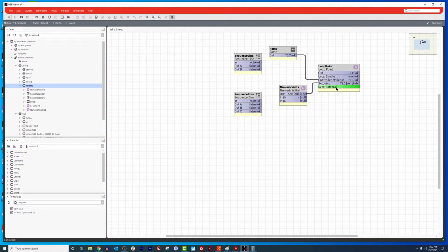Well, you first check whether you have a bias or a setup value. If you don't have a bias or setup value, and you have a proportional value and it's accurate, and you are below set point on a direct acting loop but you still have output, that's most likely integral windup. And that tells you that you have an integral issue.